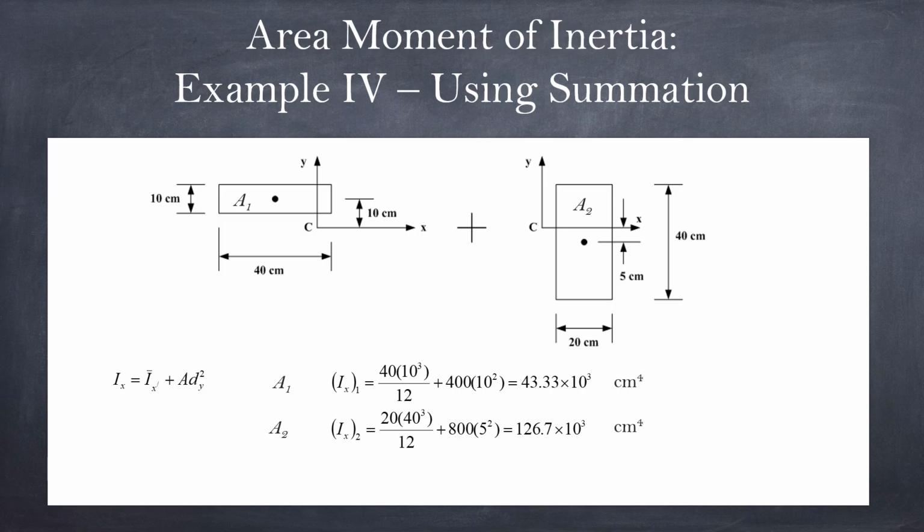Now both of them, because we used the parallel axis theorem, have already been moved to the x-axis that goes through the centroid. So what we do now is just combine them, and then we have the answer.